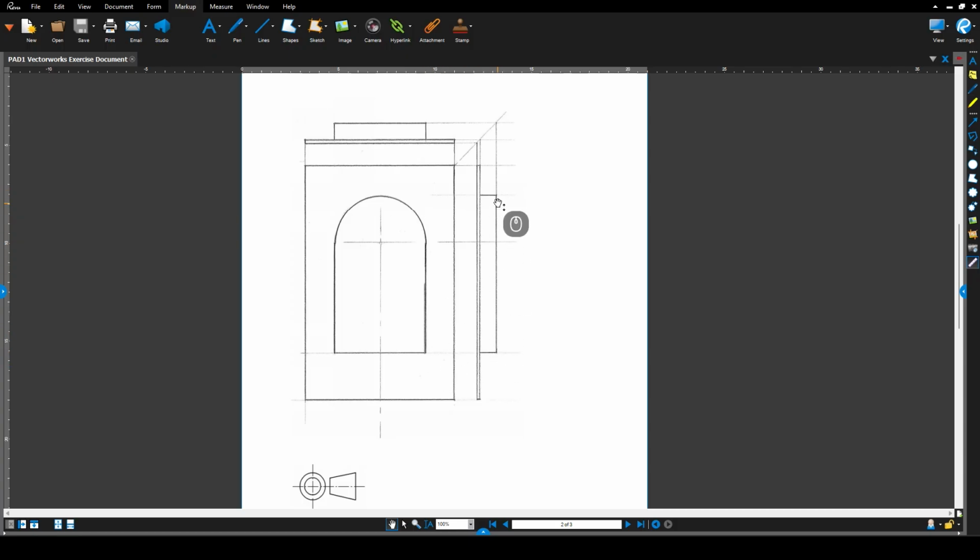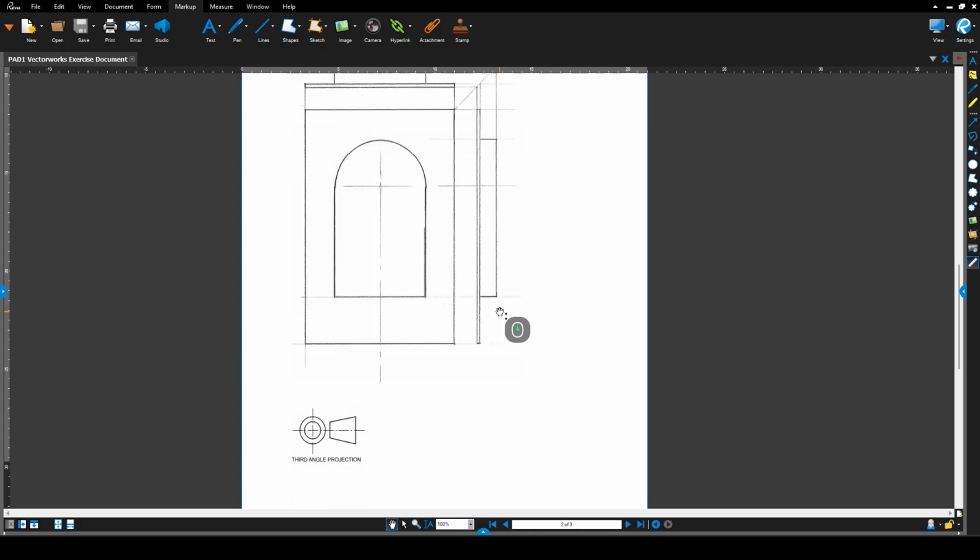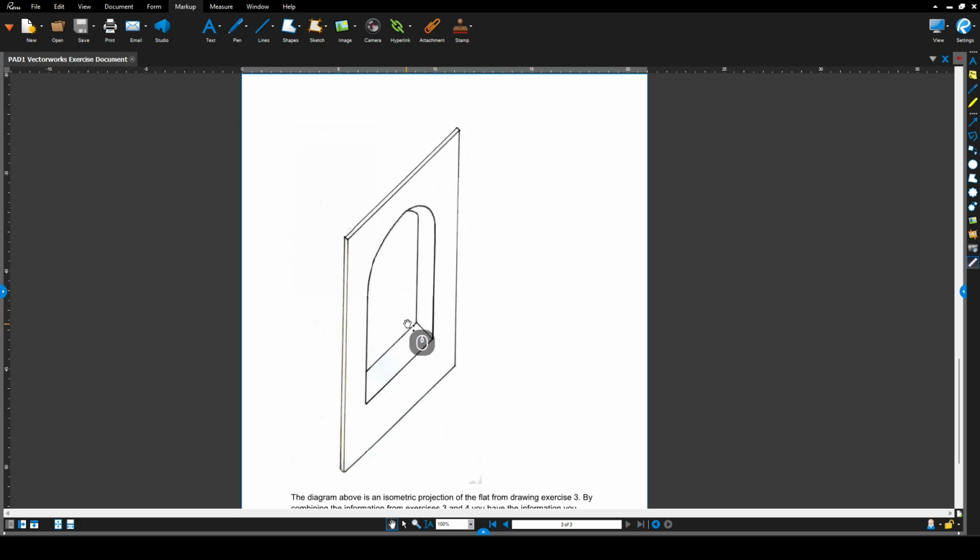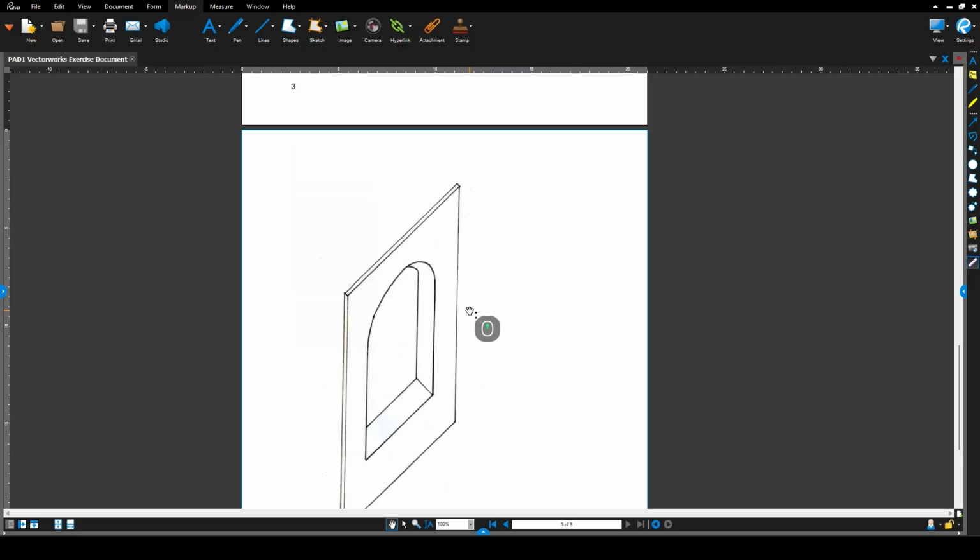The return will come back from that, and what we'll need to do is create a thickness to create the 3D object, to create this return. Here, this return isn't solid. It basically makes it look like this window has some fake depth. So if you're sitting in the audience, you would think, hey, that's a thick wall. And it's not at all, because this flat is only 25 mil. But this return is 200 mil back of the flat.